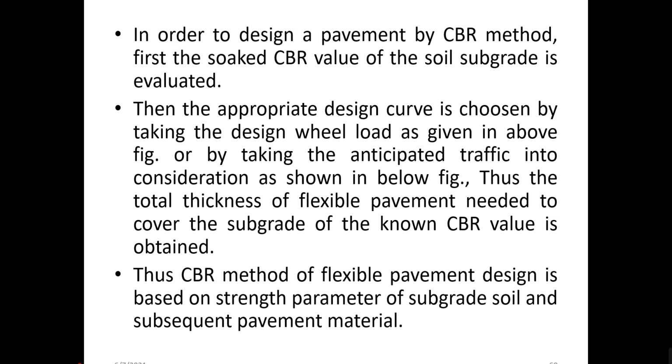So usually, why are we going to conduct the soaked CBR test? Wherever we are constructing the road in waterlogged areas, wherever the water table of the particular area is going to be higher, it is mandatory for us to collect the soil mass for doing the soaked CBR test. Such that we'll know the strength possessed by the soil in the worst condition. Even in the worst condition, whenever it comes in contact with water, what will be the bearing capacity of that particular soil, and how well that soil is going to behave with the moisture that is going to be absorbed by that particular subgrade.